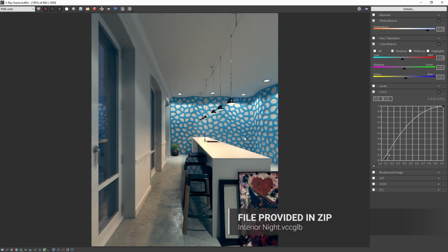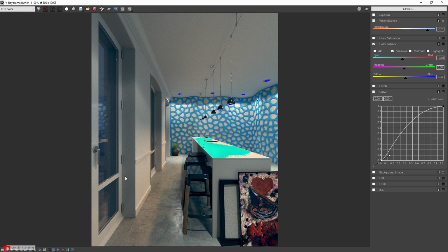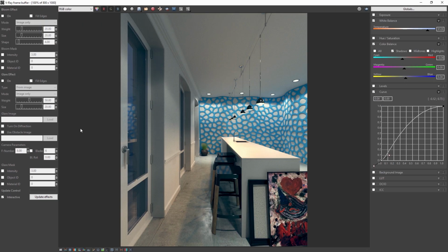Now, these areas of the image are extremely bright in the picture. Turn on Force Color Clamping with this icon and you'll see what I mean. The image is overbright in those areas. The light sources are very overbright, while the top of the counter is not too bad. We verified that in the image the light sources are where the most brightness is, so turn off the Force Color Clamping.